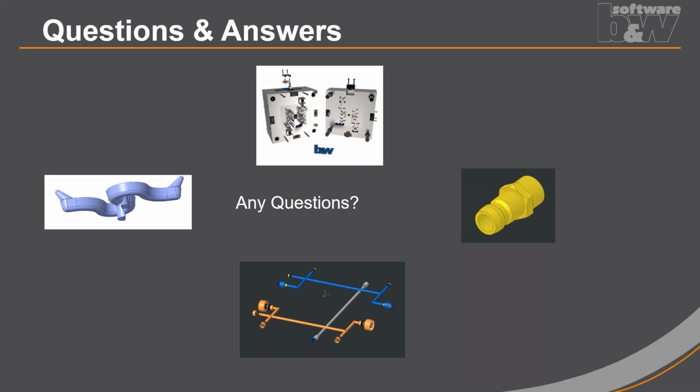And in case you already have this components folder from some old configuration or something like that, you really should clean up this folder and only leave the stuff there which was customized. The rest, which is similar or equal to standard, should be deleted from this folder. This is the best way to set up a custom configuration.